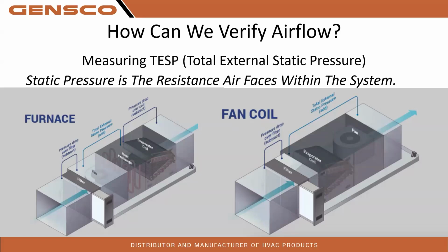field. Fan coils, your air handlers, it came out of the box with the coil. Please do not try to measure in between. You measure on the return of the unit and on the supply of the unit. And yes, that is even before the filter on units that come with filters. This is very important.